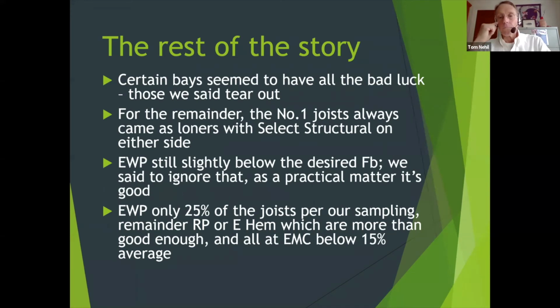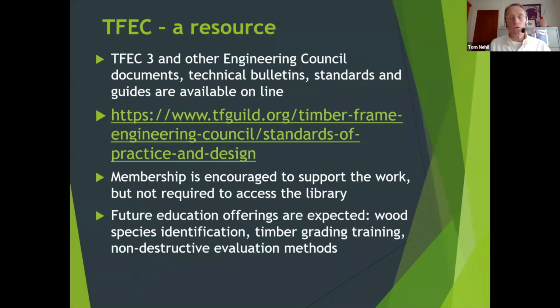So for that eastern white pine number 1, maybe on paper we're a little overstressed, 10, 20%. But as a practical matter, the whole thing is good. It's got more than enough capacity. So we told them to proceed on that basis. So it was a really good result for them and kind of saved the project, really.